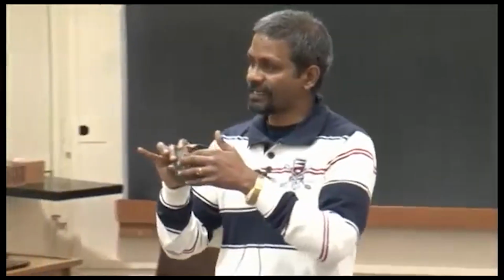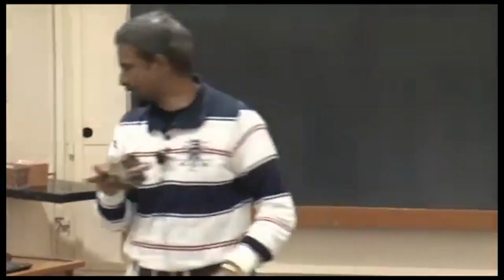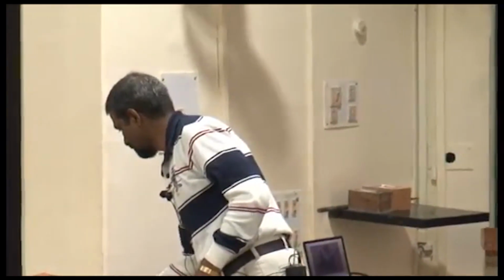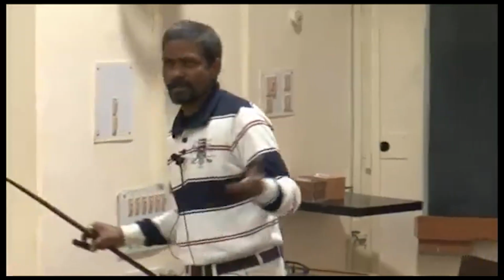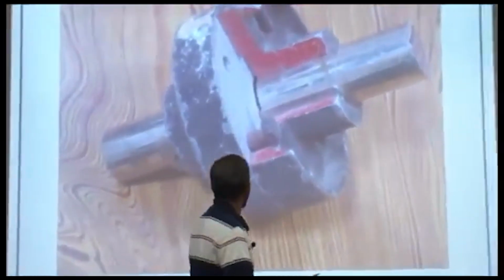This is how you're going to be sectioning your drawings. Section the main parts. Ignore the supporting elements. Ignore the fastening elements. The elements like ribs, spokes, lugs. Section the rest of the object and then bring those supporting elements back.